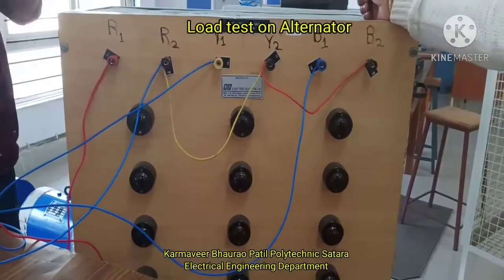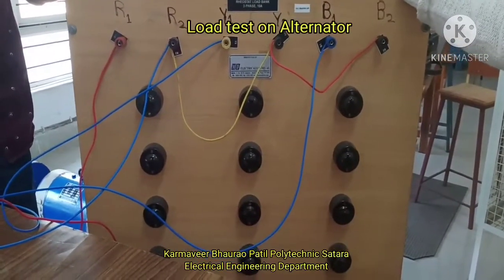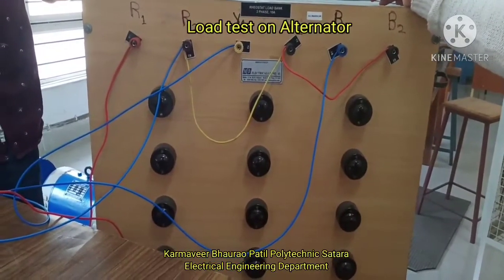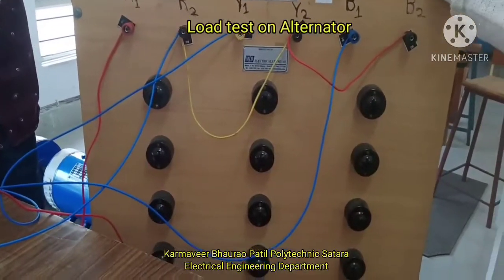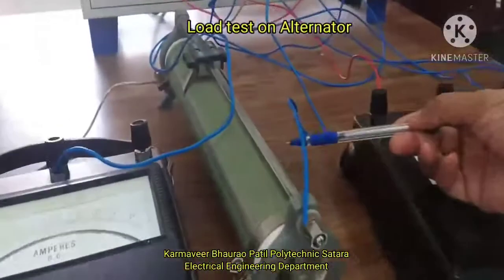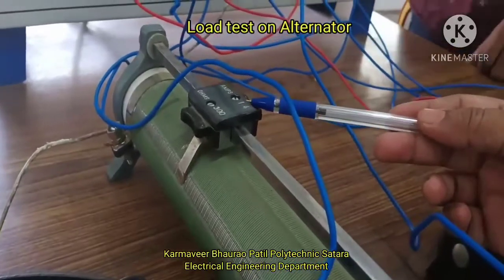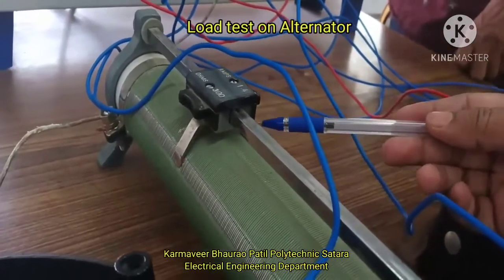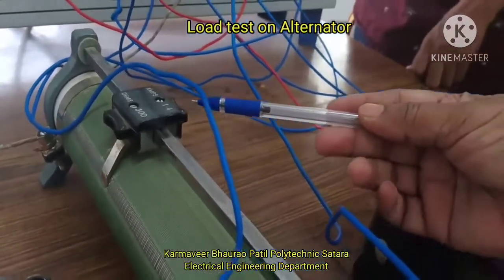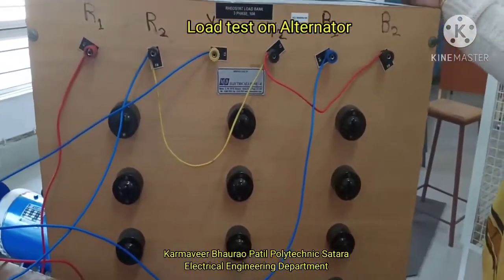Now to start the experiment, we have to connect the supply to the motor, then operate the 3-point starter. The motor will be started, then make the alternator on. First you have to adjust the speed to 1500 rpm. For adjustment of the speed, we will be using the flux control method. By adjusting the variable terminal of this rheostat, we will adjust the speed of the motor to the rated value of 1500 rpm. And then we will see how to make the load variation.